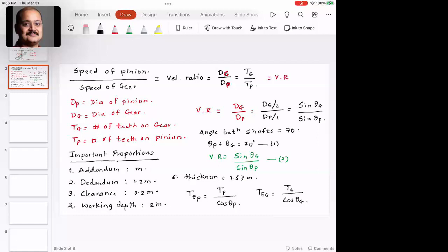To convert a three-dimensional bevel gear into its equivalent two-dimensional spur gear, please try to understand, why do we say spur gear is planar? Because if you take a plane, you would see the spur gear fits in one plane. But if you look at the bevel gear, wherever you take a slice, the dimension or what you see in that slice would be different. So in other words, you cannot approximate the bevel gear with just one slice. But if you take a slice of the spur gear, you can get all the principal dimensions.